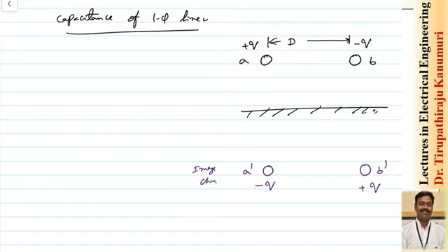Again, the height we will assume is the same, here height is equal to h. So as per the method of images, this distance I can calculate. This will be equal to square root of 4h square plus d square. This is the distance from conductor A dash to B, or conductor B dash to A. So let us try to calculate the voltage.